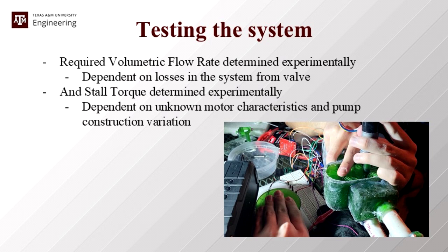This means the control system of the pump needs to account for this constant loss. While testing the system, we learned that a few design changes were necessary. First, the system had problems with leakage. That is why the final model is covered in a rubber sealant. The gear pumps also needed a redesign. The original gears had difficulty engaging and would get stuck. The paddle design improved this as it worked better with lower tolerances.